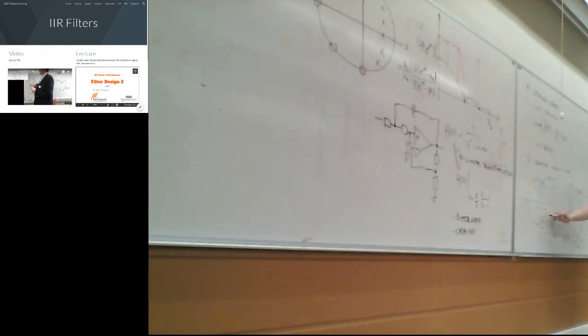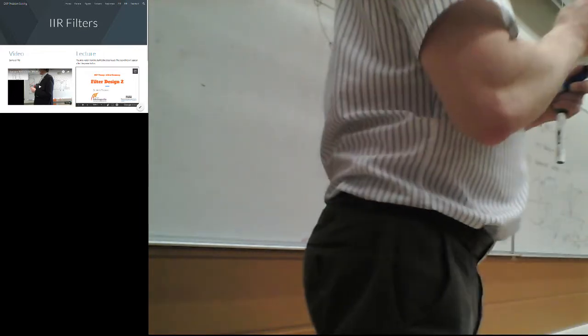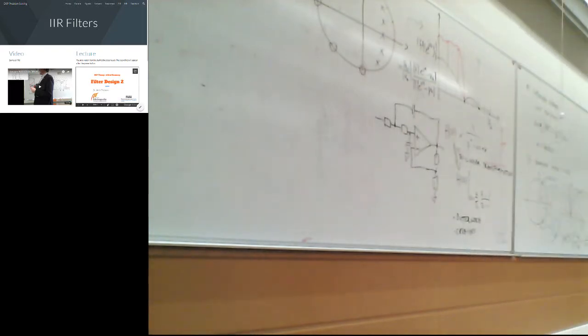And the other one, well, if you are here, basically the distances there are about 1, the ratio is about 1. So this upper distance is A, and the lower distance is square root of 2 times A. So yes, 1 over square root of 2, so it means that the amplitude there is minus 3 dB. Right. So it's directly distance on the z-plane.